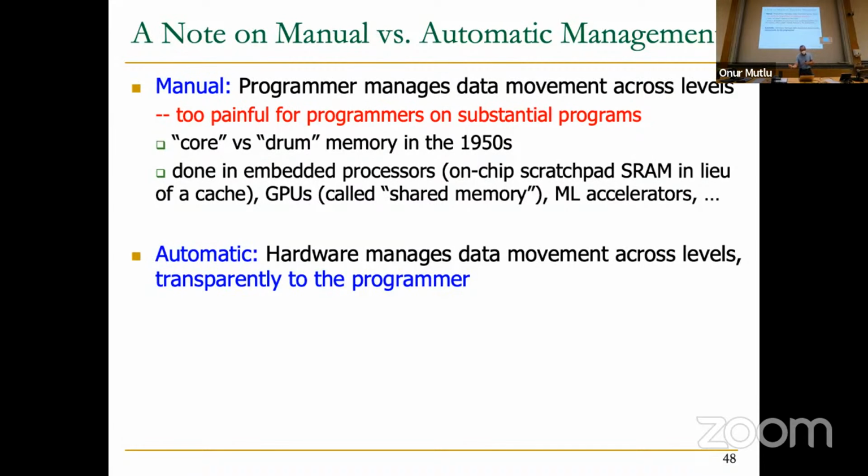Right? Okay, machine learning accelerators also have a lot of scratchpad memory, because a lot of the accesses are quite predictable in neural network computation, for example. So a programmer or the compiler can nicely manage this memory. But the key is basically you have a different address space over here that you can allocate into.